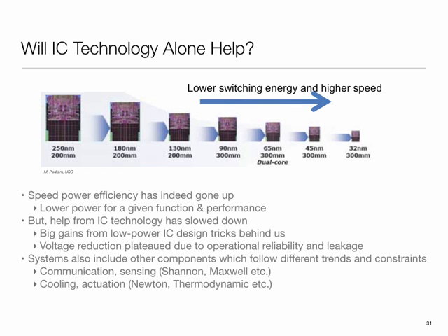Voltage reduction was a huge thing. If you look at electronics from the early 90s, they used to operate at 5 volts, then moved to 3.3 volts, then to 2 volts, 1.8 volts. Nowadays, a lot of processors, at least internally, are operating at perhaps a volt or even smaller than that. So voltage has gone down. Later on, you will see that power is related to voltage, but voltage also affects the speed. So there's a combination. I can run things at a lower power, but then I'll get useful work at a lower rate. And it's the combination of the two which would be interesting to measure. So we'll talk about it.